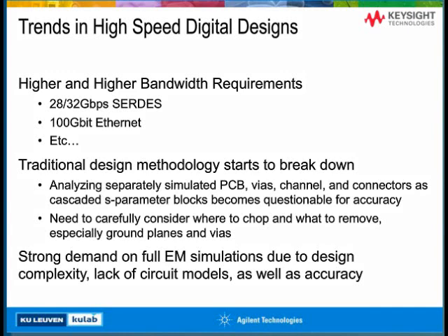So people needed to carefully consider where to chop and what to remove, especially for the ground planes and vias. This produced a stronger demand for full EM simulations due to the problems we just talked about: complexity of the design, lack of circuit models, as well as the need for higher accuracy of the analysis.